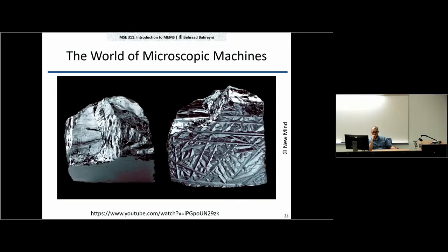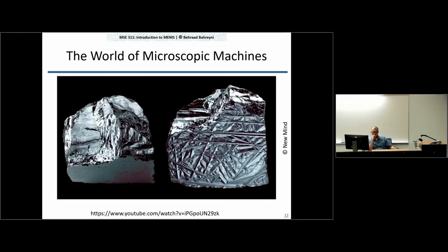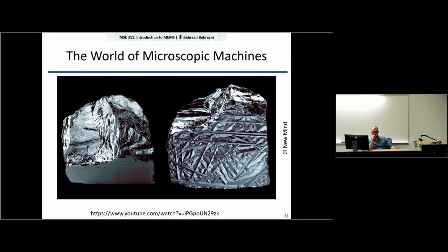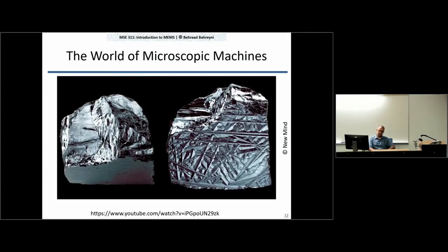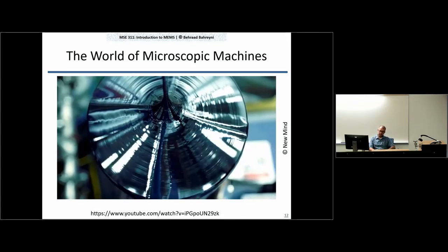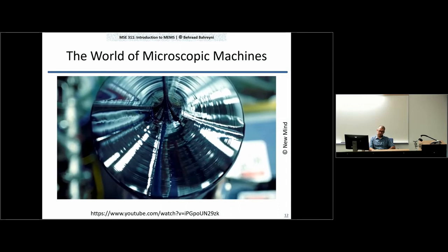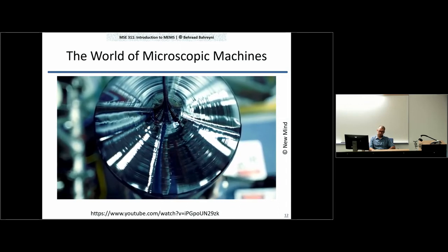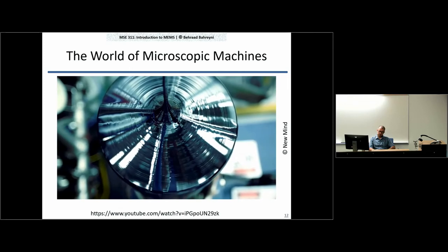Aside from its electrical properties, silicon has excellent mechanical properties as it forms the same type of crystal structure as diamond, though much weaker, and it is harder than most metals. It's also surprisingly resistant to mechanical stress, having a higher elastic limit than steel in both tension and compression.